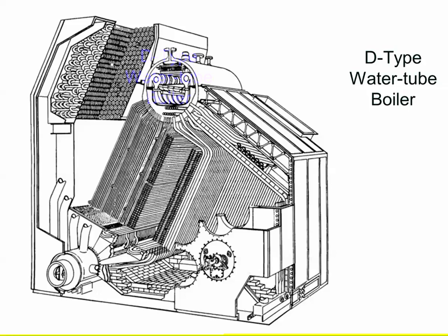Well, like I said, these steam cargo pumps are fairly small and compact, but they're typically only about 2 stages, compared to a main engine, which is, I'm just guessing, say 16 stages. So there is a lot of heat from a cargo pump that is just being dumped into the condenser. They're not efficient at all. That's not the point. You're only running them for 12 hours. And I want compact. I don't want to have a bigger engine room, which means I have to carry less cargo. So they use a high volume of steam. Going back to the Kenai, 24,000 ship horsepower main engines, about 8,000 in 4 cargo pumps.